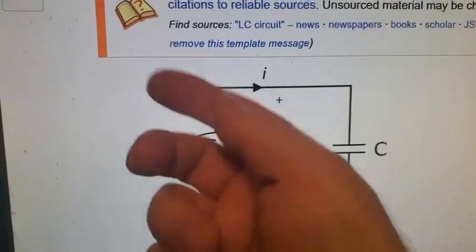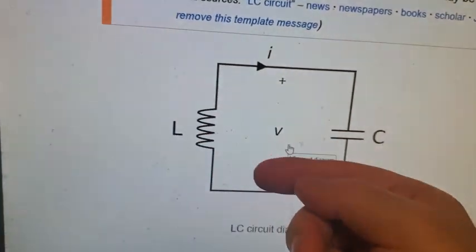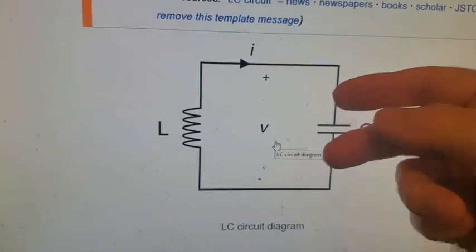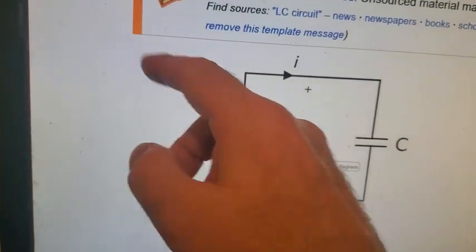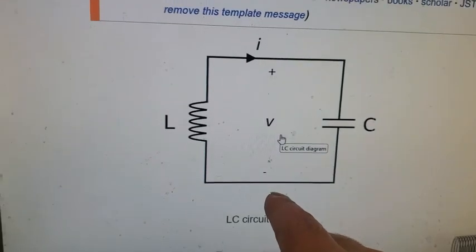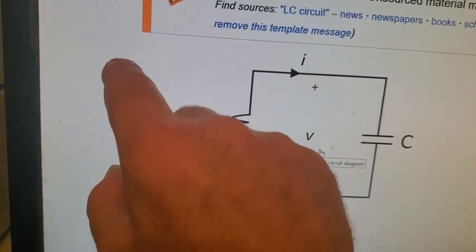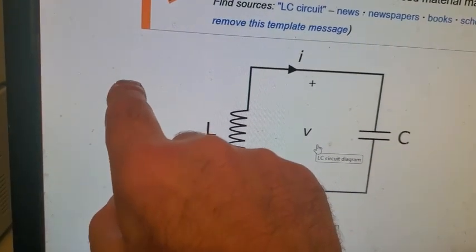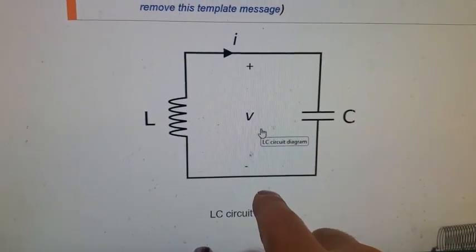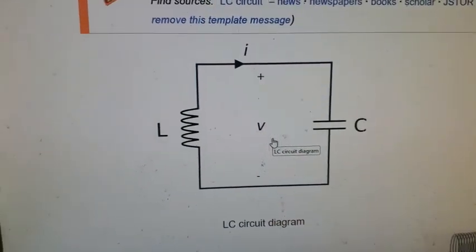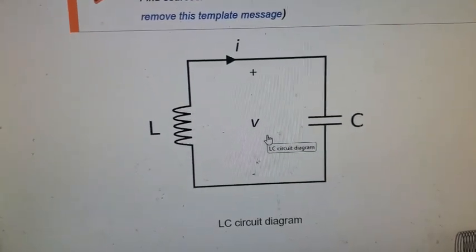What if I just disconnect, say this diode going out to this other one, instead of disconnecting the cap from the inductor, just disconnect the diode right at the 0 point, and now you'll have your cake and eat it too, because now you'd have a strong pulse that transforms voltage very well, and then this is going to go back to -9. And so I did that, and it didn't work. In fact, it was spectacularly bad.